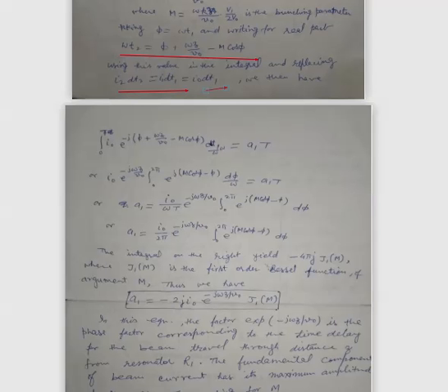Omega t equal to 2 pi, here it is used, and the integral on the right hand side of this equation will yield a value minus 4 pi j J1(m), where J1(m) is the first order Bessel function of argument m, and hence the value for A1 is obtained as A1 equal to minus twice j I0 e raised to the power minus j omega z over v0 into J1(m).